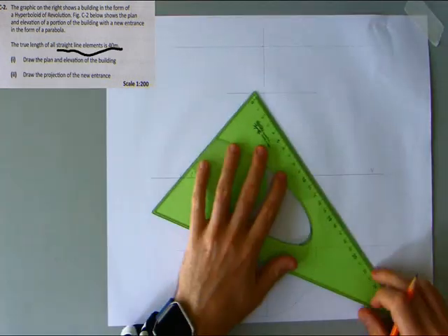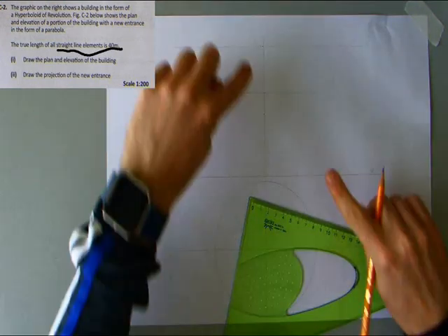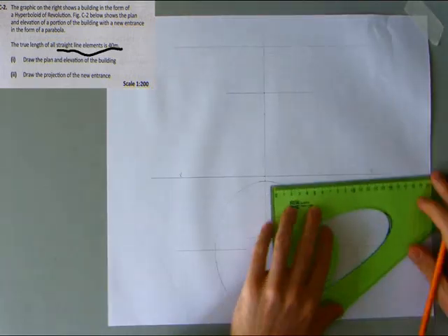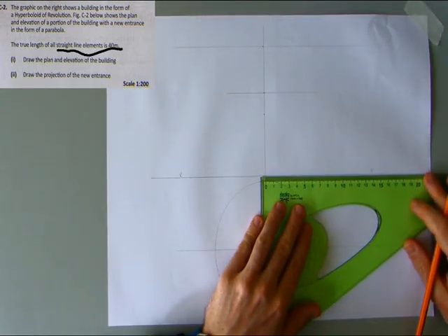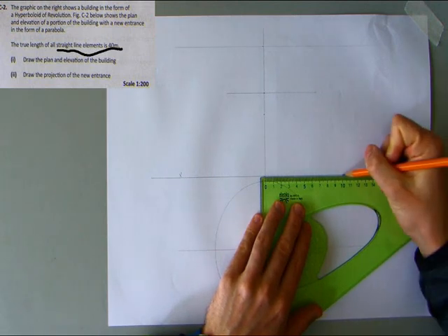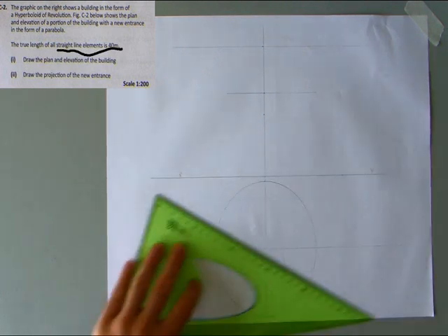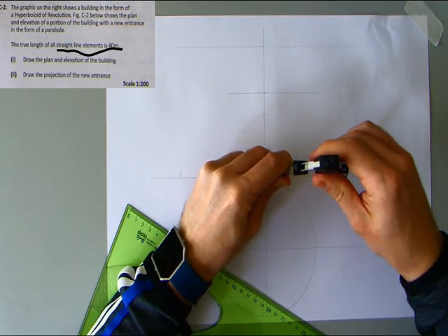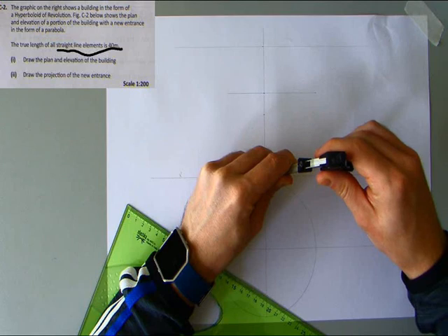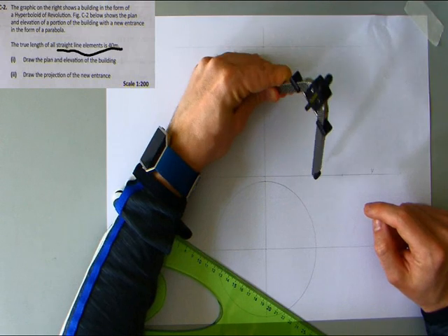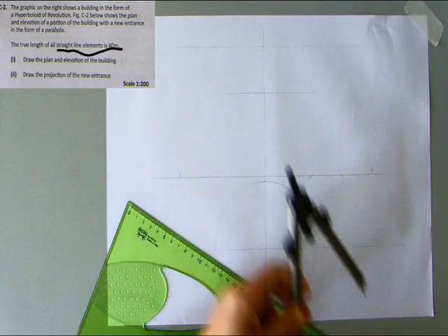Okay, so what we're going to do is, we know that our full length element is going to be 40 meters. So that means from the midpoint to the base is going to be 20 meters. So if I measure that out, I can have my measurement again to scale. This is a 20 meter line, scaled down to 200 is actually 100 millimeters. And if I mark that on the center there and swing it down here, that's my base point for what we call our asymptote.